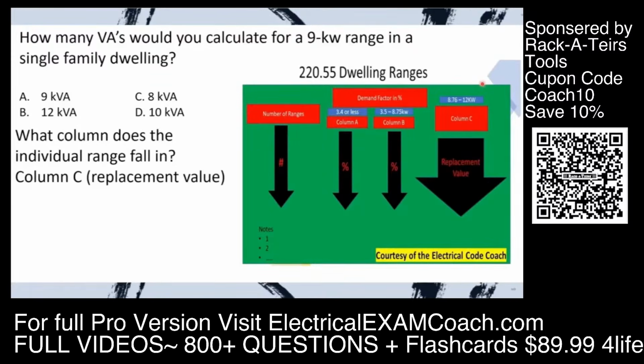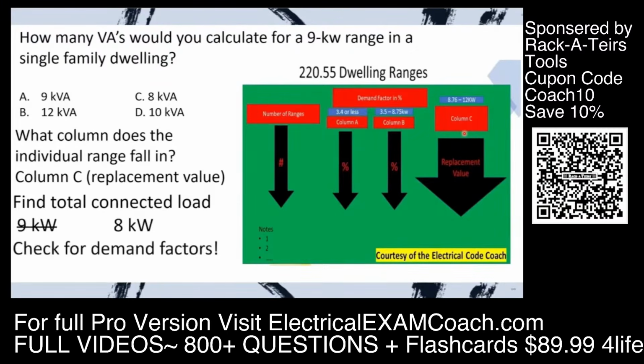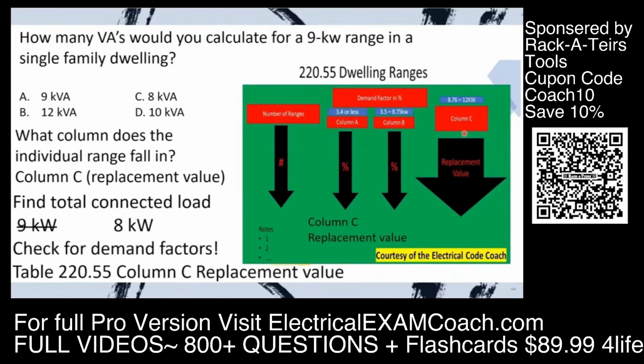Now let's find our total connected load. On the left-hand side, we're going to find our number of ranges. In this case, it's 1. Then we're going to cross all the way back over to column C and find that our replacement value is 8 kW. Then, just to stay in practice, I want you to always be familiar with checking for demand factors. But in this case, in Table 220.55, column C is a replacement value. It is not a multiplier, so we're just going to select C. Great job.